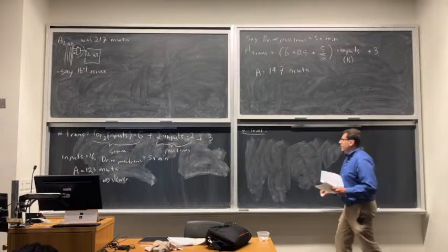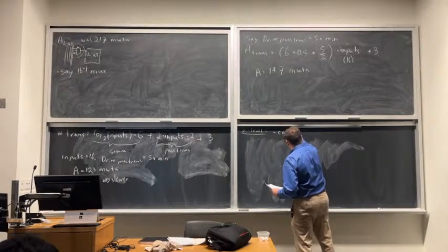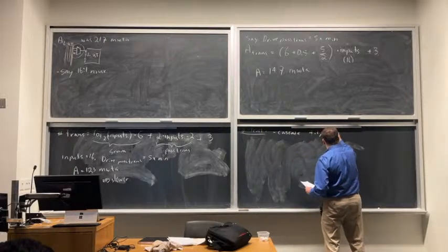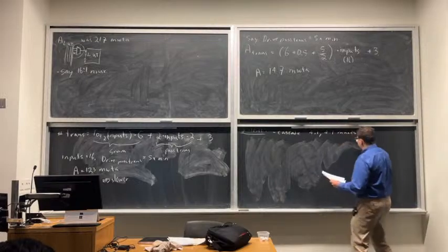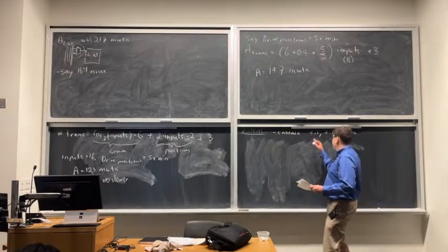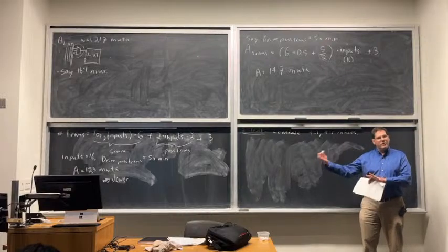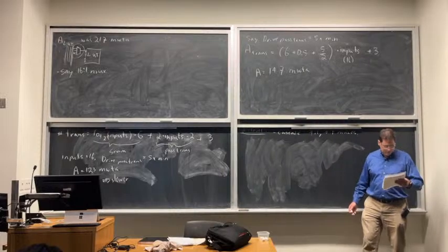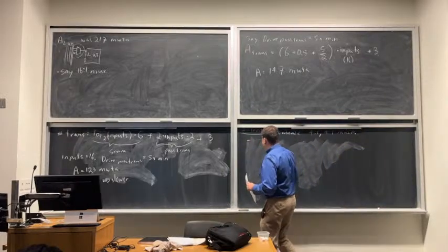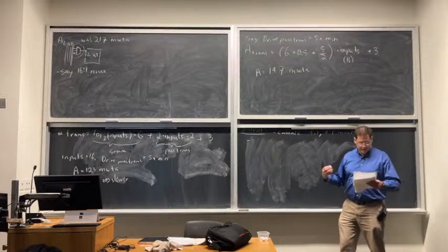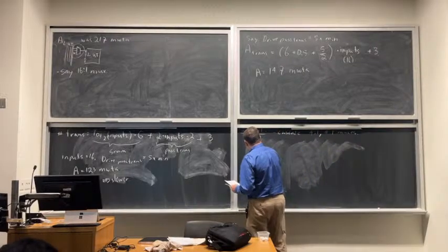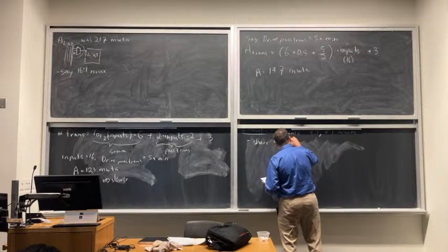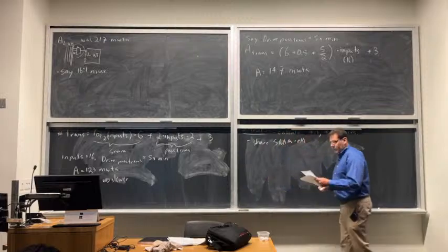So a 2-level mux is basically made by, for this one, 16 inputs, we're going to cascade 4-to-1 mux, and then another 4-to-1 mux. Okay, so if we had 4 4-to-1 muxes, and then they produce a 4-bit output, we can put that into another 4-to-1 mux, and we get our 16-to-1 mux function. That doesn't gain us anything unless we apply a trick. The trick is we have to share the SRAM cells across all the first-level muxes.